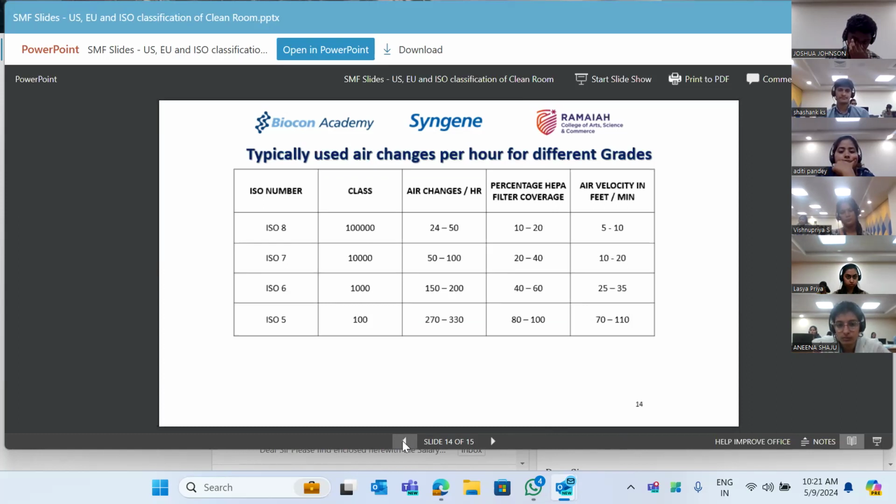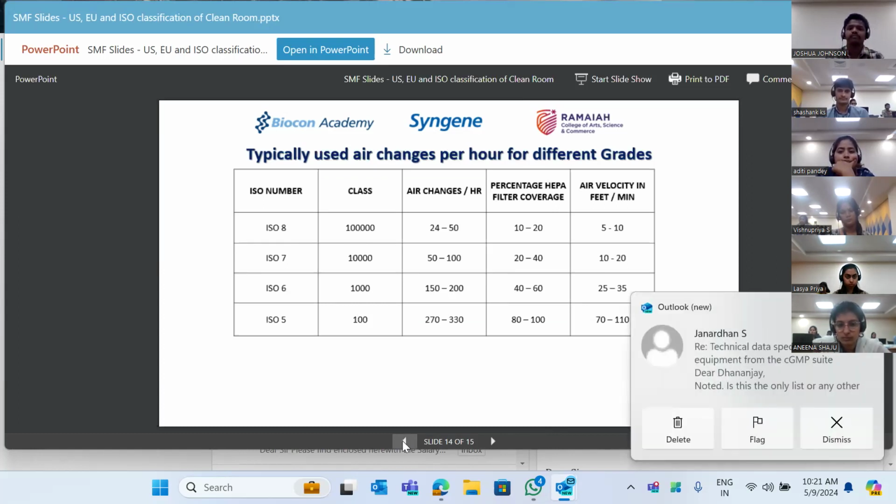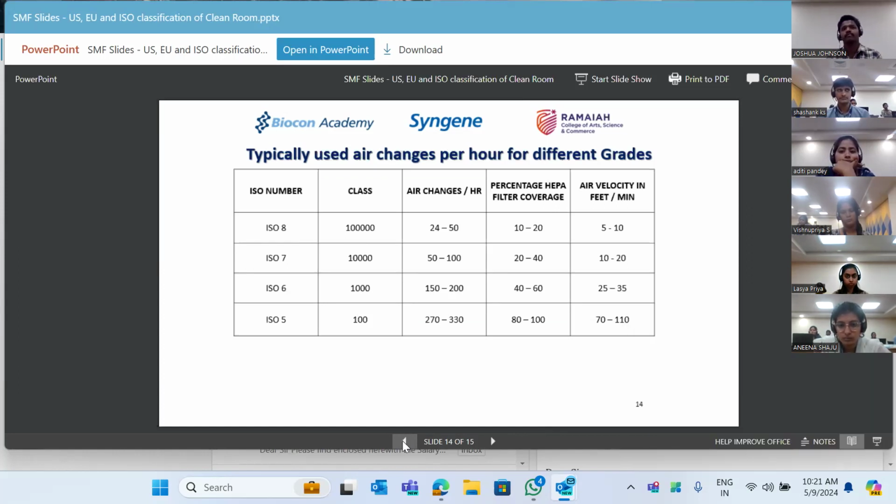So this was a summary of what I wanted to tell about the various classifications which are prevalent and how they are all interrelated to a greater extent. But importantly, they are all meeting the clean room environment requirement in terms of the air changes, temperature, humidity, or the particles which are allowed within the given space. Microbial counts, like for example, I said that the new ISO 14698 controls the classifications of that. So this is a summary for this particular small topic of classifications.